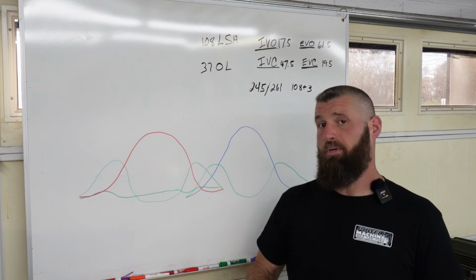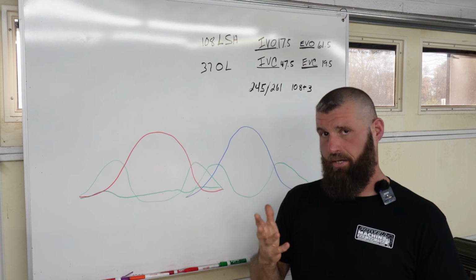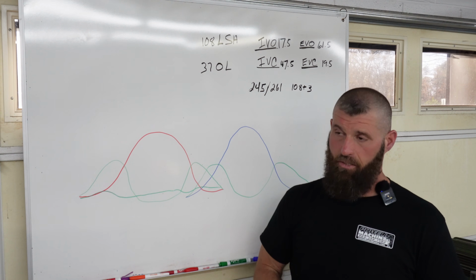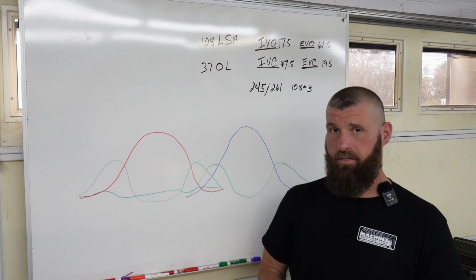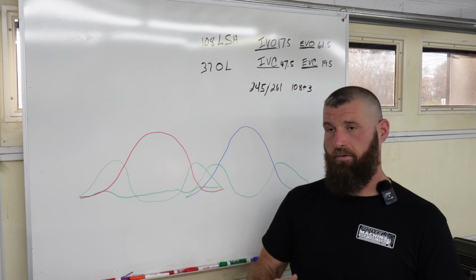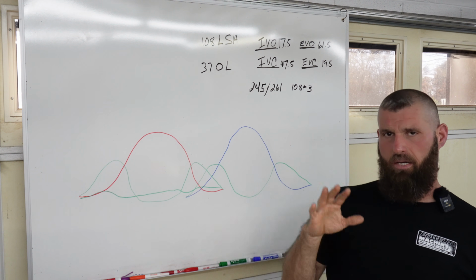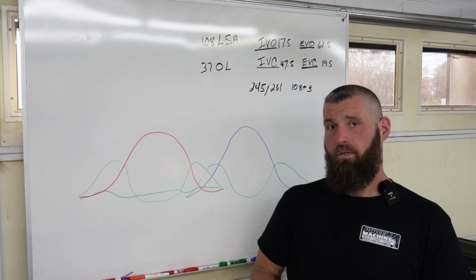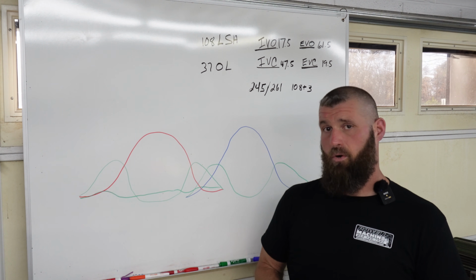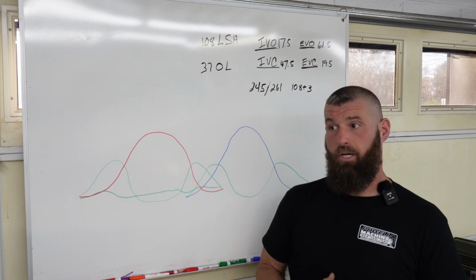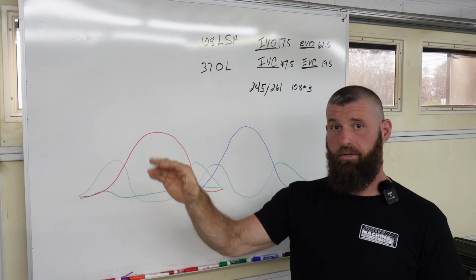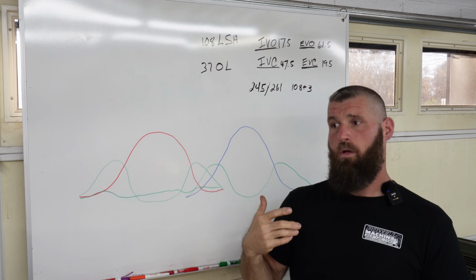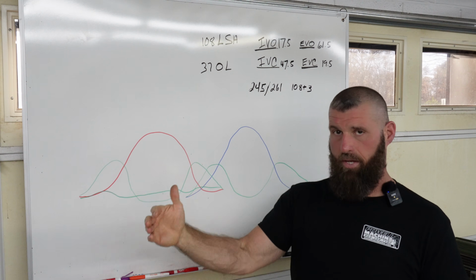And it might fool me, it might go a little further than that, but I expect about 400 or 500 more RPM to peak. You know, we expect it to carry a little beyond that, right? I mean, most of the time, unless you're just absolutely out of cylinder head, it'll carry for another 300 or 400 or 500 RPM. And I've seen some stuff with lots of cylinder head, it'll carry another 600, 800 RPM. You know, it's all airflow dependent. How long can it maintain?